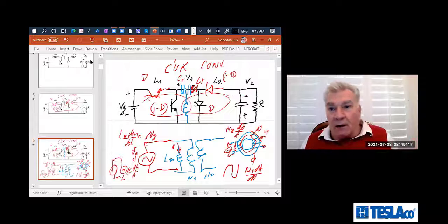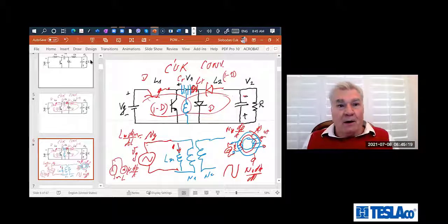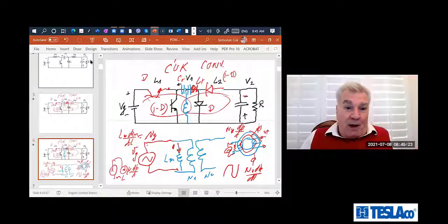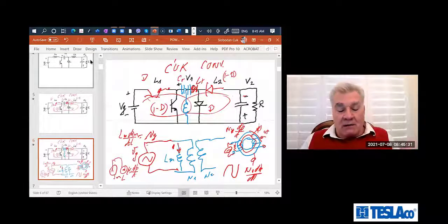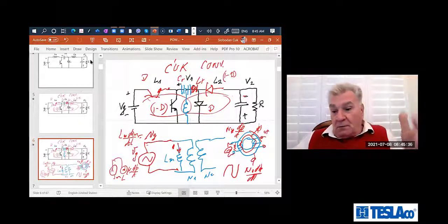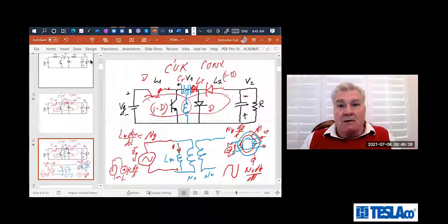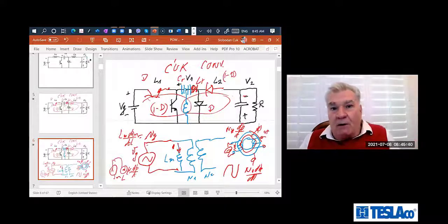It's a wasteful current. And that's why in 60 Hertz transformers there was a push to say, can we make a magnetic material with 10 times higher magnetizing inductance, by making the permeability of the core 100,000. Like, a 60 Hertz core has a permeability of 100,000.